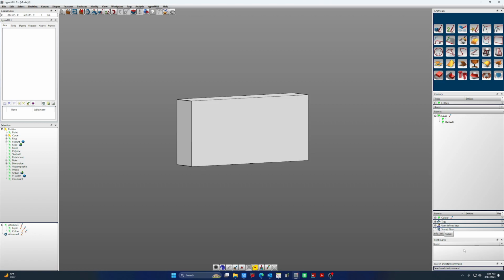Bookmarks are actually super cool, probably a little underutilized, but you can think of a bookmark in the CAD workspace, in the hyperMILL or the HyperCAD-S workspace, it doesn't impact CAM, as a snapshot in time. So your screen orientation, your view orientation, the colors, the transparency, what layers you have activated, you can basically take a snapshot in time.